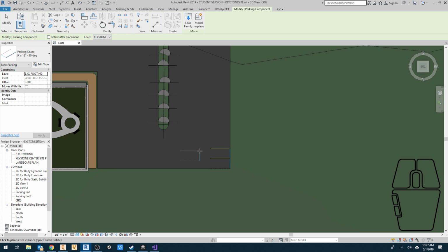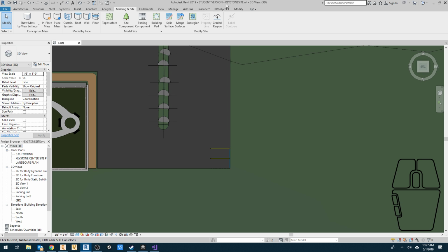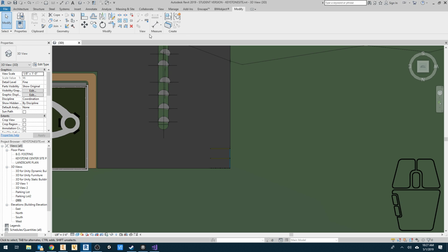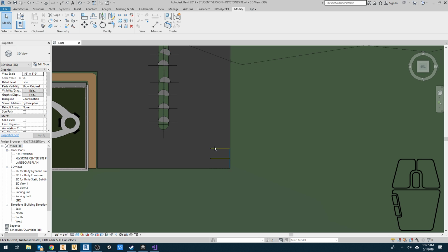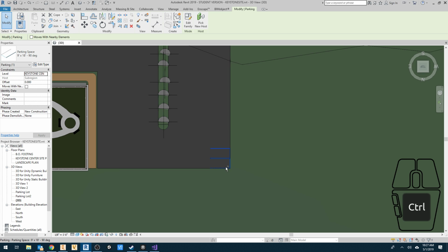Let me show you. If you haven't done it yet, I'm going to show you one of my favorite tools. So let's go to Modify. And under my Modify tab here, I have Array. An array is a grouping of things. Super useful. How many of you have used an array so far? Okay. So I'm going to select the things first. I'll select that one and select that one. I got two things. Revit likes you to pick the thing you want to modify first. So pick it, then click what you want to do to it. I picked them. Now I'm going to click Array.